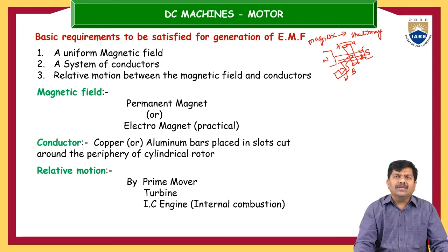Now if you are constructing any electrical machine with the help of these permanent magnets, size also matters here, because a strengthened magnetic field means the size of the permanent magnets also proportionally increases. If the permanent magnet size increases, the size of the electrical machine also increases, which is not advisable. So that's why permanent magnets are replaced with electromagnets.